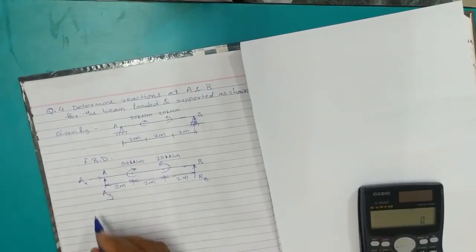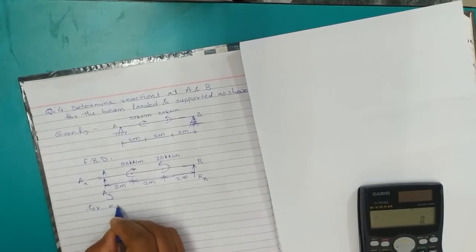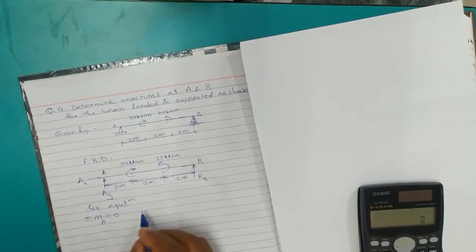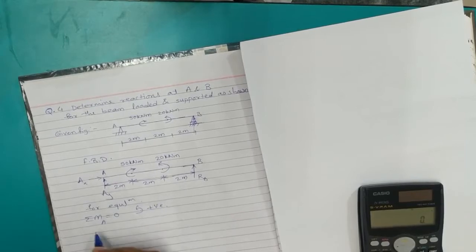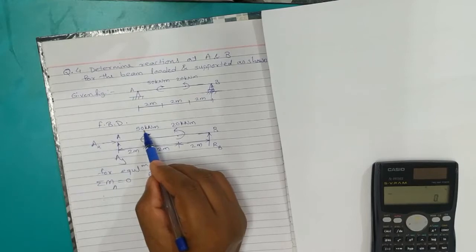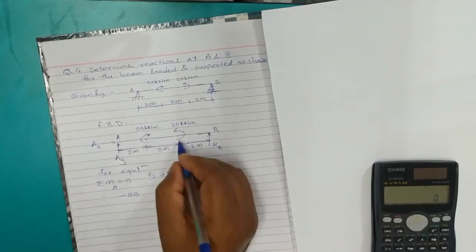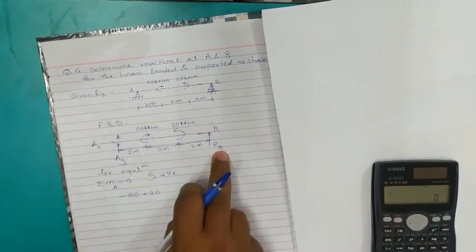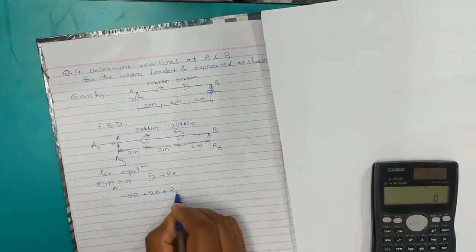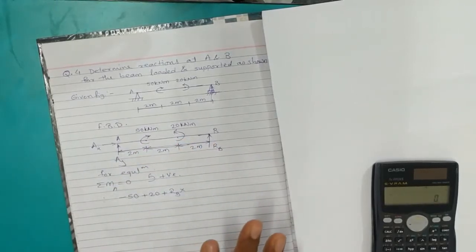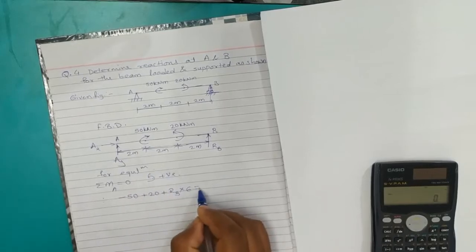Now we have a hinge point, so without any doubt, for equilibrium we will apply the condition summation MA equals to 0 about the hinge point, taking anti-clockwise positive. So moment of AX and AY about point A is going to be 0. Here we have got a clockwise rotation 50 kilonewton meter, which should be taken negative. Anti-clockwise rotation 20 kilonewton meter should be taken positive, and the moment given by RB will be again anti-clockwise. The load should be multiplied by the distance. We have not multiplied these moments by any distance because those are already moments, remember. RB should be multiplied by 6 and should be equated to 0.